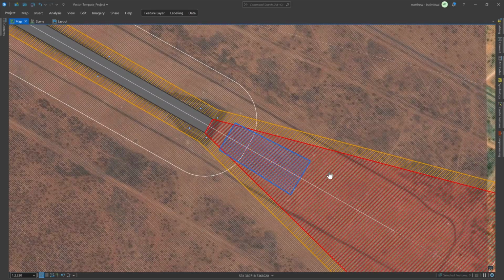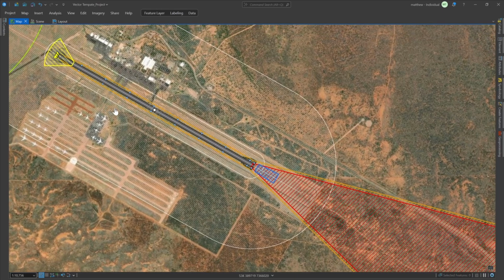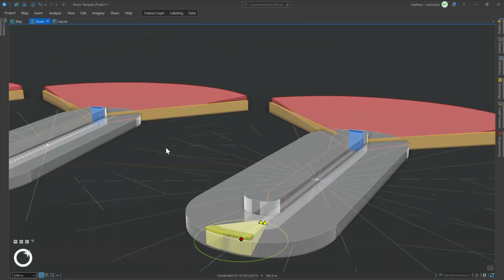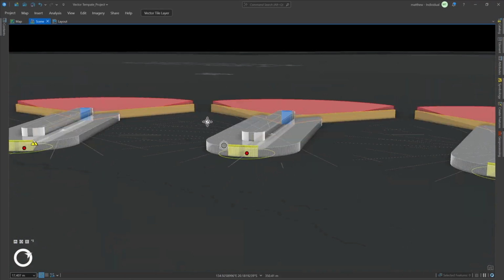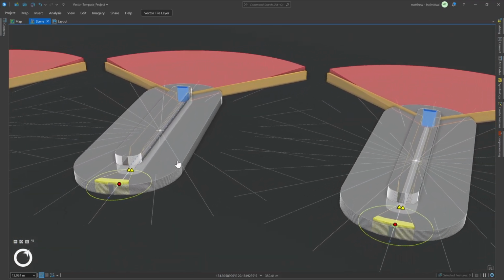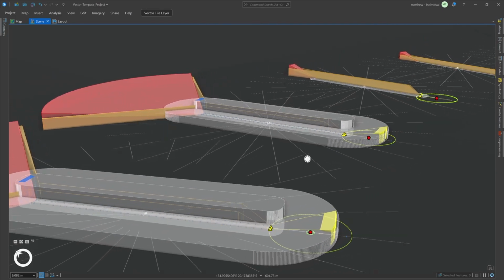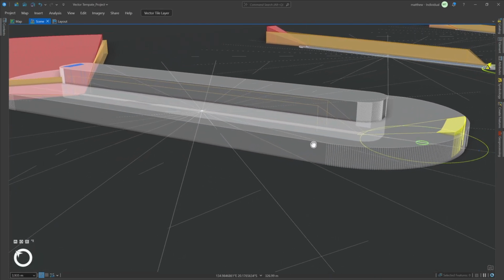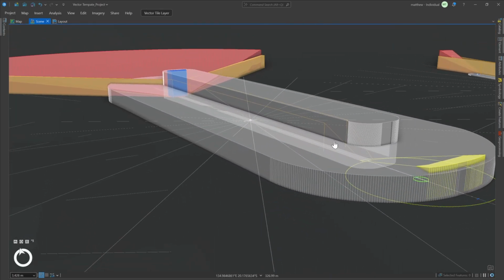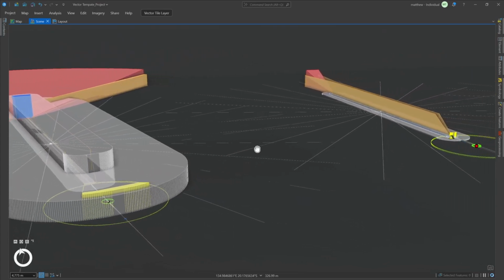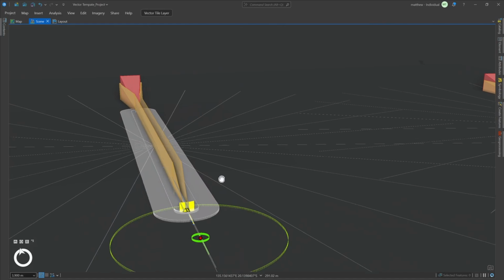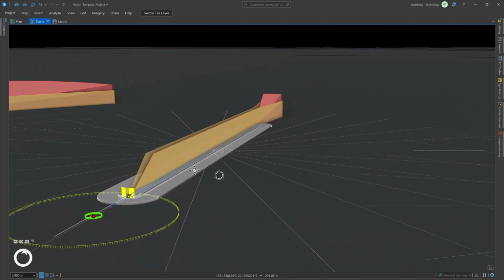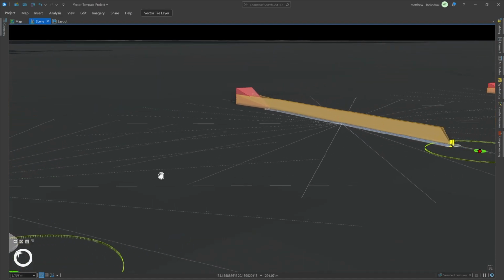So what exactly have I created? At its core, the Dynamic Geometry Constructor uses a feature for its datum, this example using a feature line. This designates the left edge of the runway as the datum. The tool intelligently reads the geometry and attribute information from this line. Based on that input, the tool then performs the creation of numerous associated points, lines, and polygons. This vector information also includes Z values for vertical height, making it powerful for 3D analysis and planning.